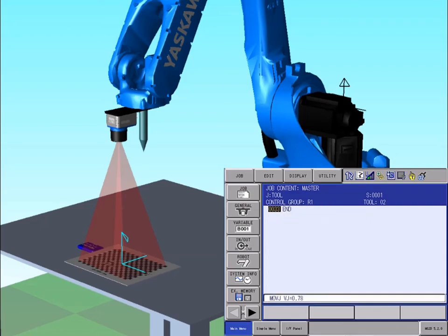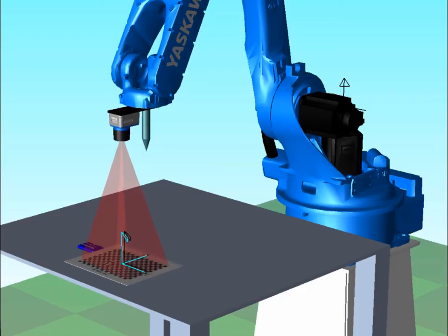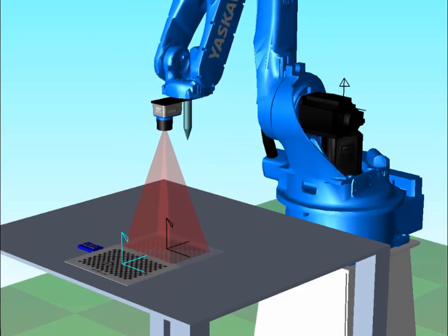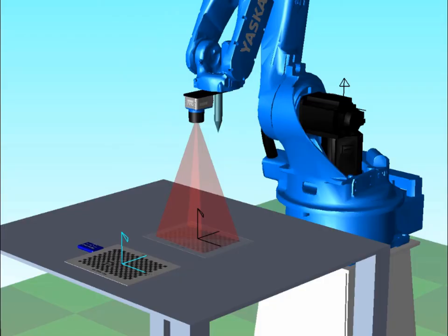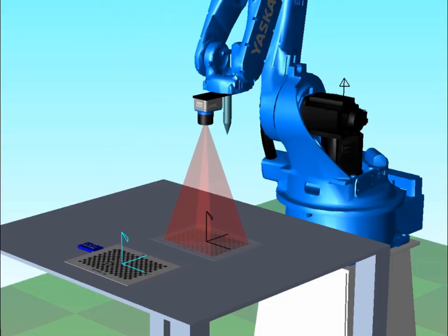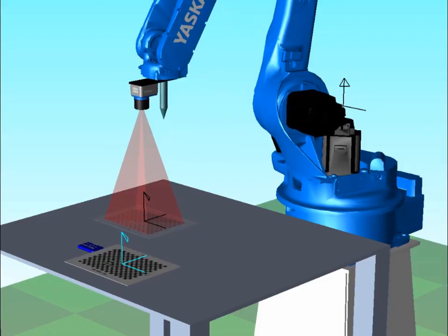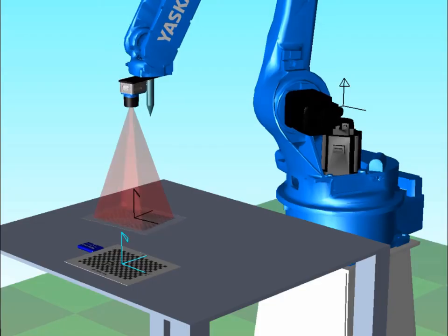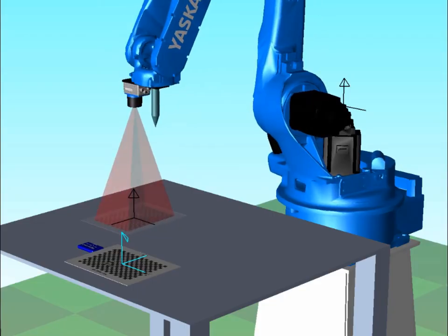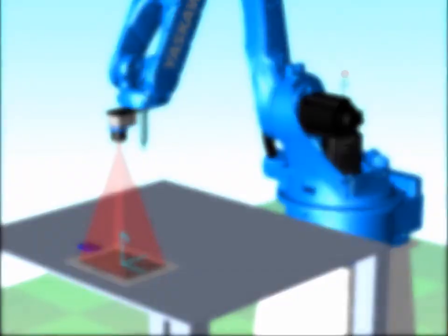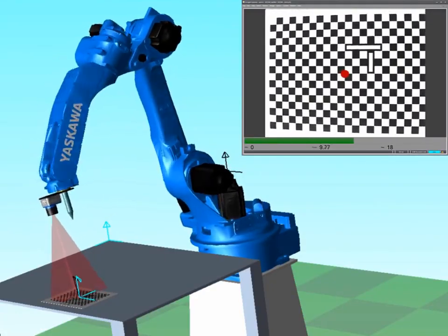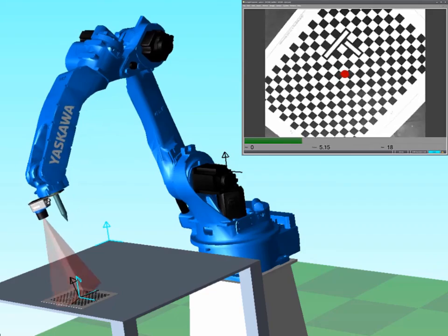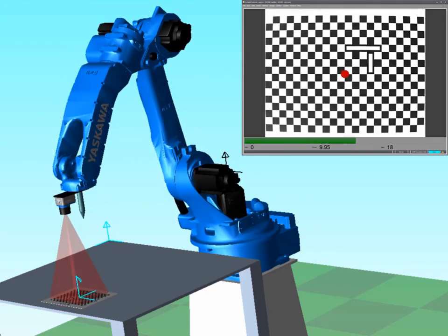Once we execute tool job, tool number 2 is created exactly at the origin of user frame number 2 with the same x and y axis direction. Now we can see that when we move the camera to a different position, the camera TCP represents the origin of the camera frame. And any data passed to the robot can be converted from tool frame 2 to robot base frame. So any patterns found by the camera can be related to each other even if the camera has changed positions.